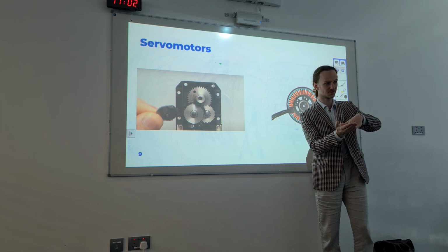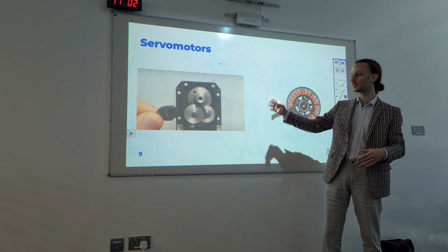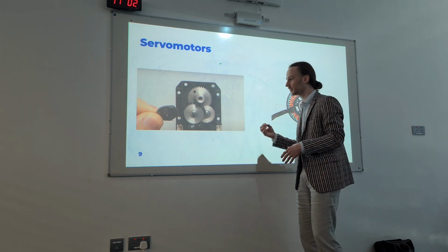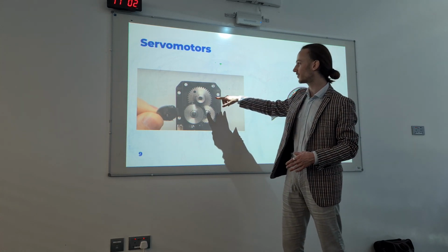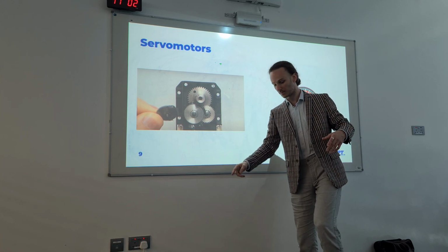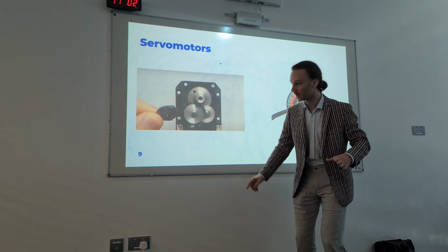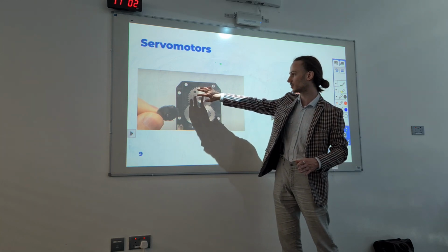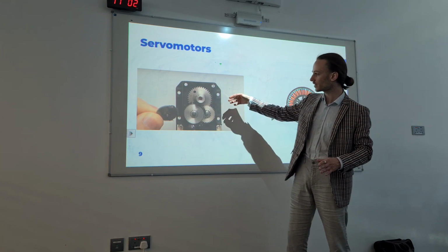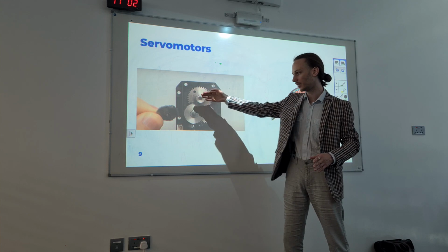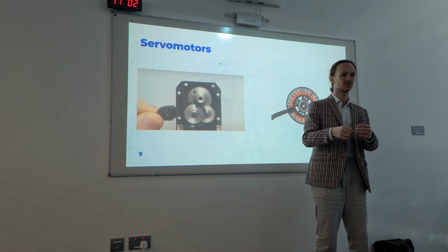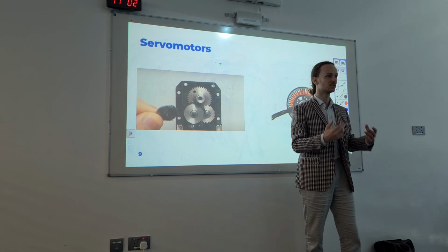It's soft, but it's really fast enough. And the problem with these servo motors is that they cannot do that. They're not reactive that much. And if at the moment of contact a high torque is being applied to this gear, this torque is propagated through the whole gearbox up to the rotor, and the rotor has to start moving very rapidly, and that's not possible.